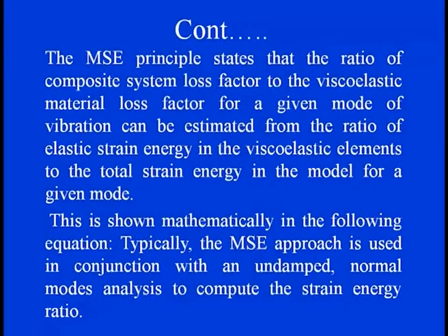So, this principle states that the ratio of the composite system loss factor, because we know that when we are talking about the viscoelastic feature, there is always a loss factor, to the viscoelastic material loss factor for a given mode of vibration can be estimated with the ratio of elastic strain energy in the viscoelastic element to the total strain energy in the model for a given mode.